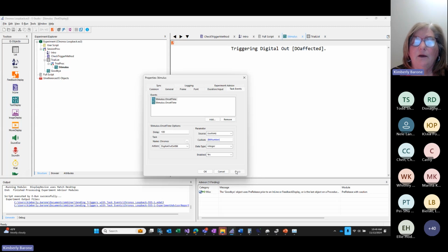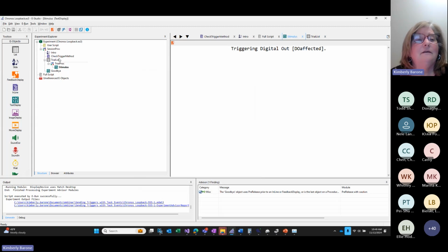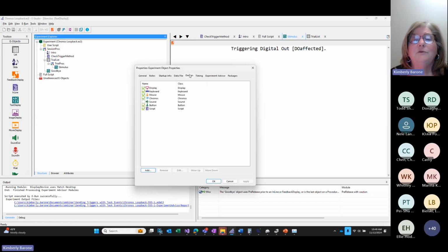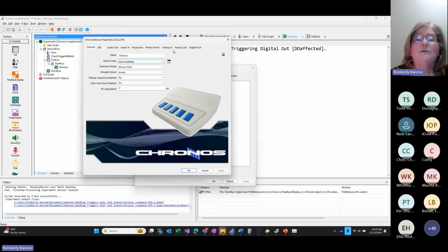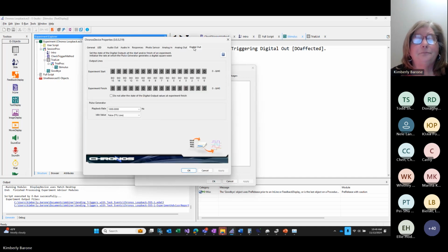So, let's just look at that real quick. How would we actually set both of those bits? Well, if I'm not remembering my binary math very well, I'm just going to pull this up on the digital outs. And what if indeed I wanted to set 14 and 15 high? Well, it turns out that corresponds to integer value 49,152. So if I wanted to set both bits high, I could call write integer 49,152. And that's going to set both of those bits high until I choose to set them back down again.